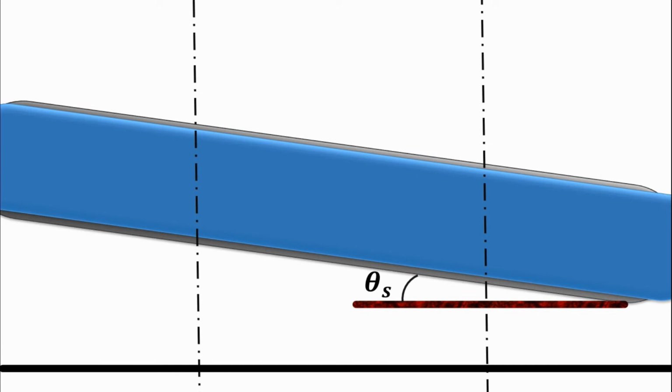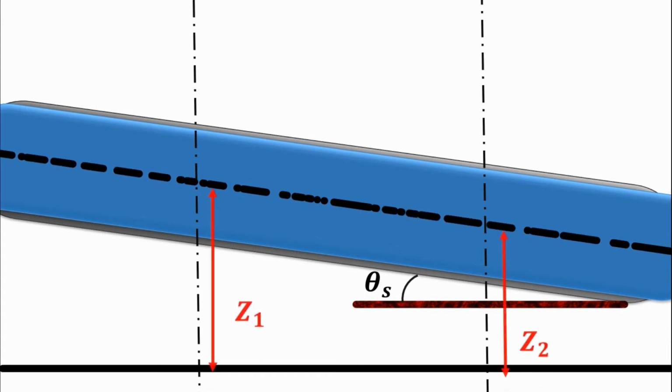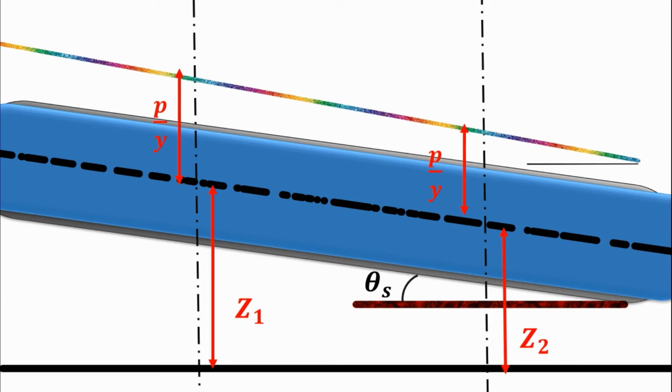Now, let us consider a section in a pipe flow, that is a conduit, in which a free surface is not available. That means the pipe is flowing full, at heights of z1 and z2 from datum, and the pressure heads in the considered section are measured from the line joining the center of the pipe flow. The line joining various points of pressure head is known as the hydraulic gradient line, which is above the surface of the conduit in pipe flow.